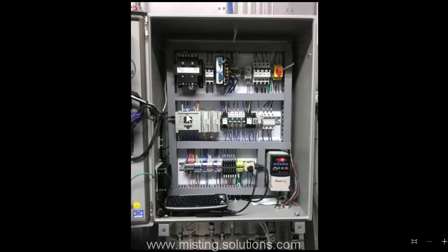It's one of these wires that is up here, and it tells the system as a whole to run. And then the third set of wires that we talked about were the common alarm relay, and from here, the landing point, they go to this particular relay right here, and that is the alarm relay, or the alarm cube relay. Anytime the system, the microcontroller, senses an alarm and goes into alarm, it energizes that particular relay.